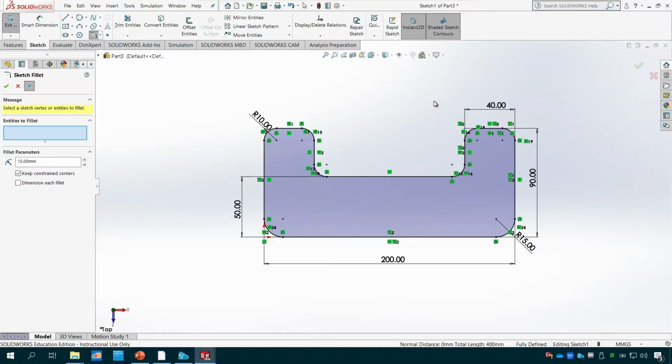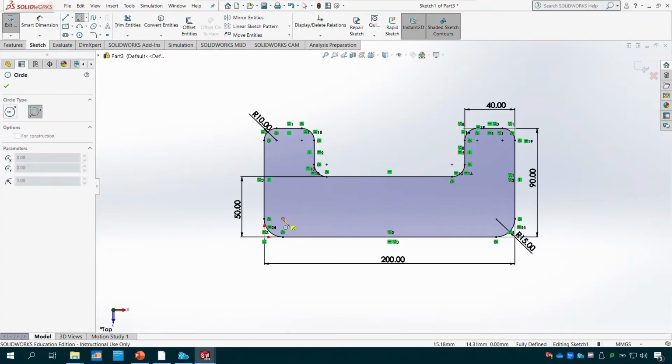And what I'm going to do, I'm going to go and make the 2 circles. If you go to the exact point, because that radius was 15, then I no longer need to find the center of it. Make sure also the circle you're using is this one, the circle with the center, not the perimeter circle. So I'm going to go there and make the circle.